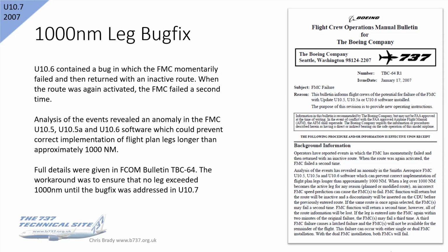There was another bug where, if you had a leg that exceeded 1,000 nautical miles, and who does that, then the FMC would fall over and fail. Well, there you go. I cannot think of a time I've ever used a 1,000 nautical mile leg, but if you ever did, that's what would happen.